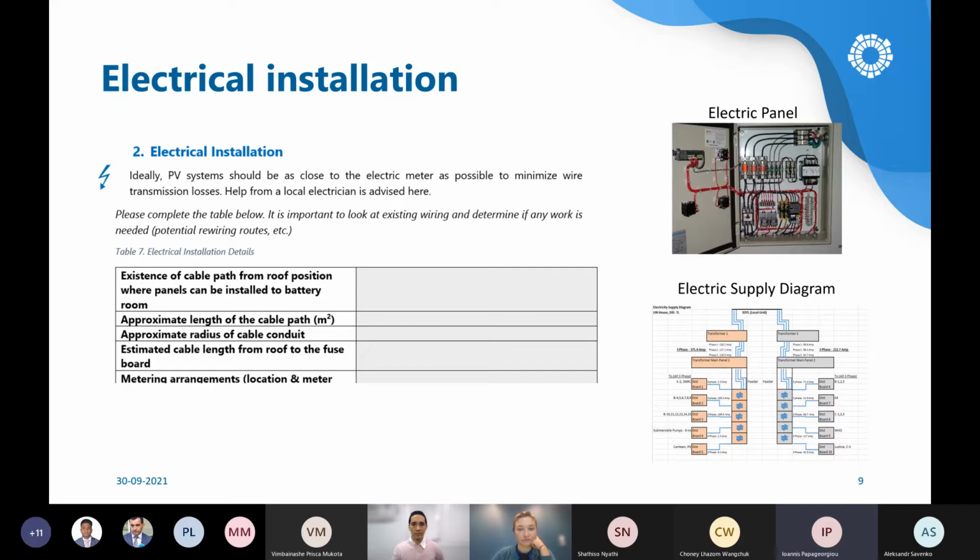We will install power monitoring devices called grid analyzers to the grid output and also the genset if you have. And then we'll move with some simpler devices called PCMMs in the premises, in the distribution panels of the buildings. That depends on the critical loads that you might have or on each floor, depending on what you feel above in the site survey. But as I said, it's good to have a supply diagram which is updated. If there are major changes, let us know.